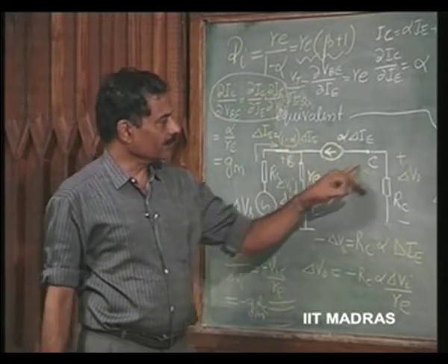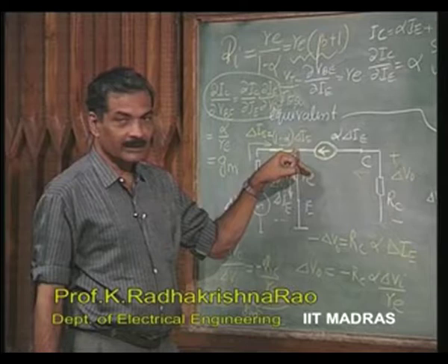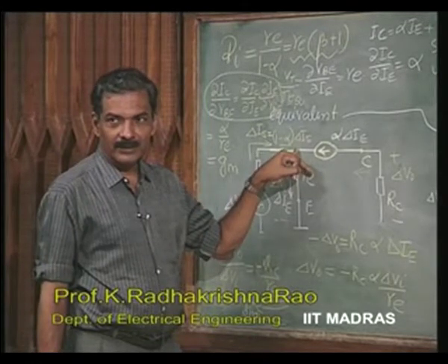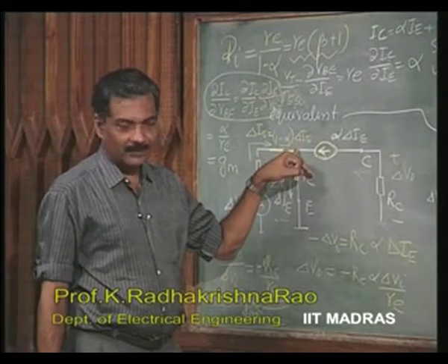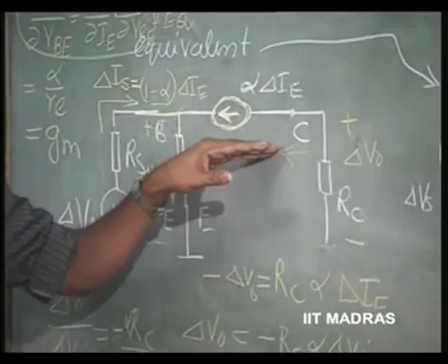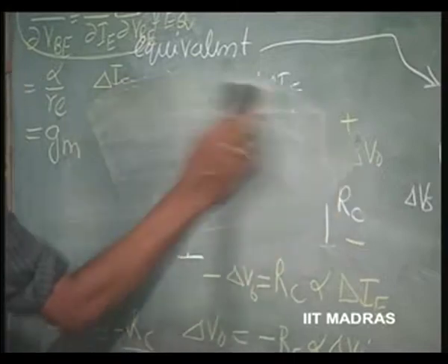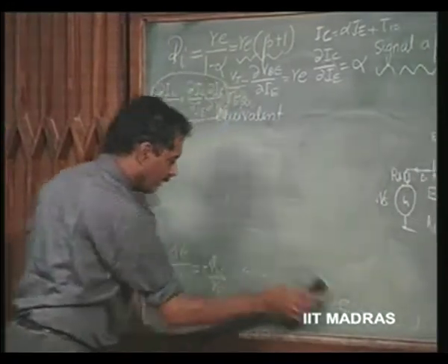If of course there is a high resistance, indicating some leakage resistance, between collector and base, then of course there will be finite output impedance. So, it is enough if we learn this basic thing about the common emitter amplifier.